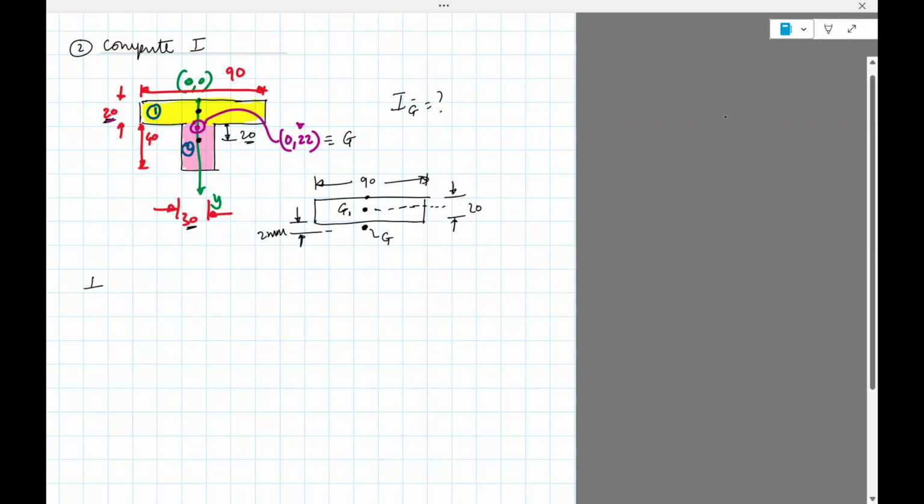Okay, now what I'll do is to compute, let's call that G1 bar, okay? So that's the centroid of the complete system, but I want to compute for 1. So I just have a notation, say G1 bar. So that would be I of G1 plus, there's something called parallel axis theorem, which tells you what's the inertia about an axis not passing through the center.